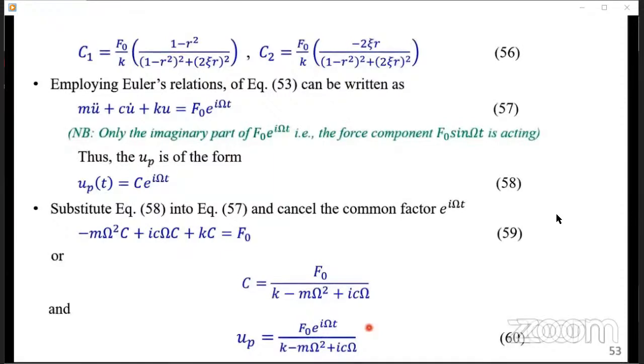Like now, if you were given a multi-story building in Nairobi to analyze, and you assume there is no damping, then it becomes interesting. Why did you assume that? Because we are saying you already know the different types of damping that will occur. There is damping even from external sources, just because of the fluid, the air; the structure is vibrating in air, it's not in a vacuum.